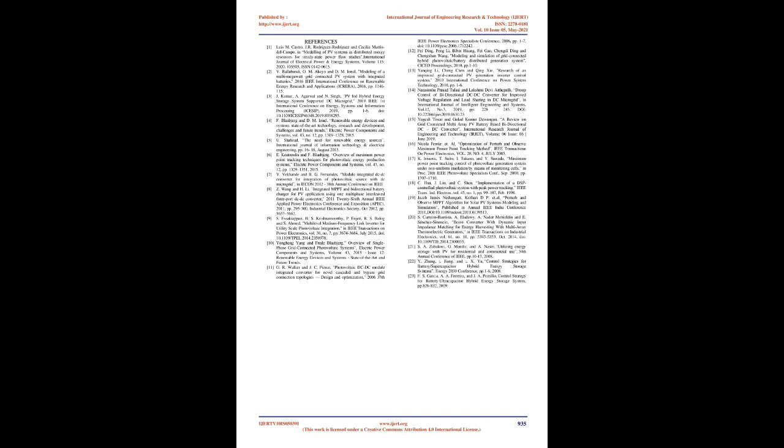When the system is in steady state, solar irradiance is 1000 W/m2, and temperature is 298 K. From Fig 10, it is known that at this condition, the maximum output power of the PV system is 2000 W, but due to switching and operational losses the system produces an output of 1800 W before 0.5 seconds. As the insolation level goes down below the STC condition, there is a slight fall in output of the system, generating output power of 1280 W following the MPP region. As the insolation starts gaining its level, the PV system with the help of MPPT can track the radiation and regains its original MPP point at time 2 seconds.